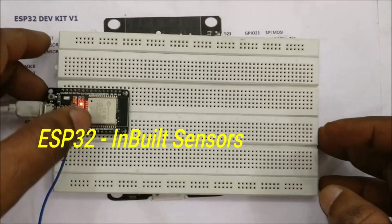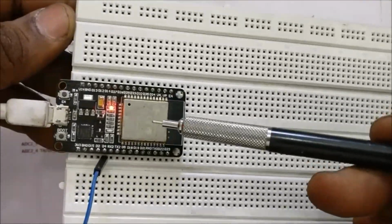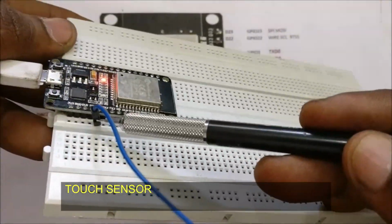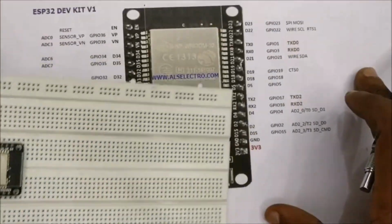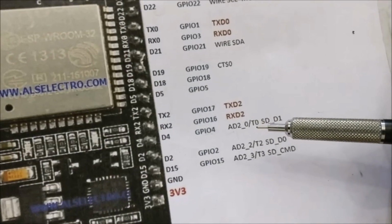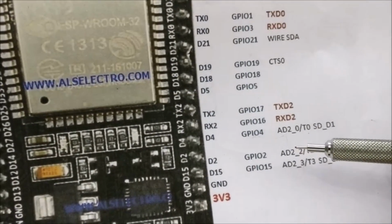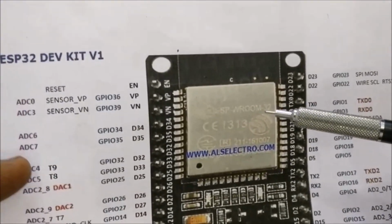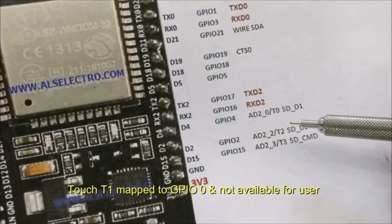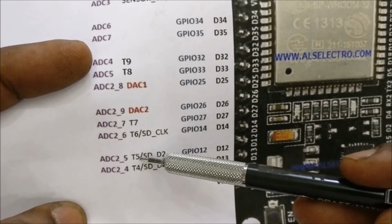Hello all. In this video we will see the inbuilt sensors of ESP32. First is the touch sensor. There are about 10 sensors, T0 to T9, which are multiplexed with other pins on ESP32. The T1 sensor is not available for the user and it is mapped to GPIO 0. The other sensors are available, T0 to T9 except T1. We will be using T0 in this example, which is mapped to GPIO 4.